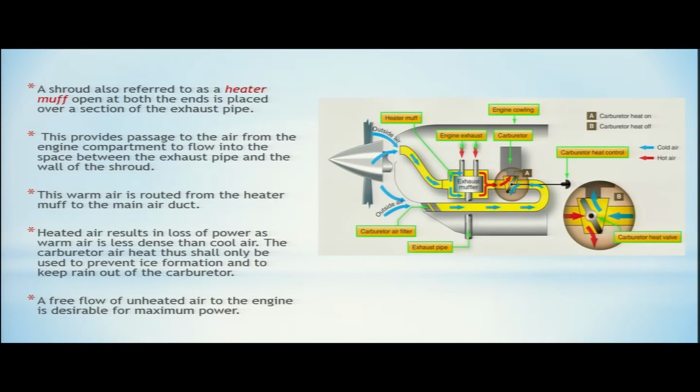Now this heated air has its own disadvantages. The disadvantage is that heated air will result in loss of power since it is less dense than cool air. The carburetor air heat thus shall only be used to prevent ice formation and to keep rain out of the carburetor.